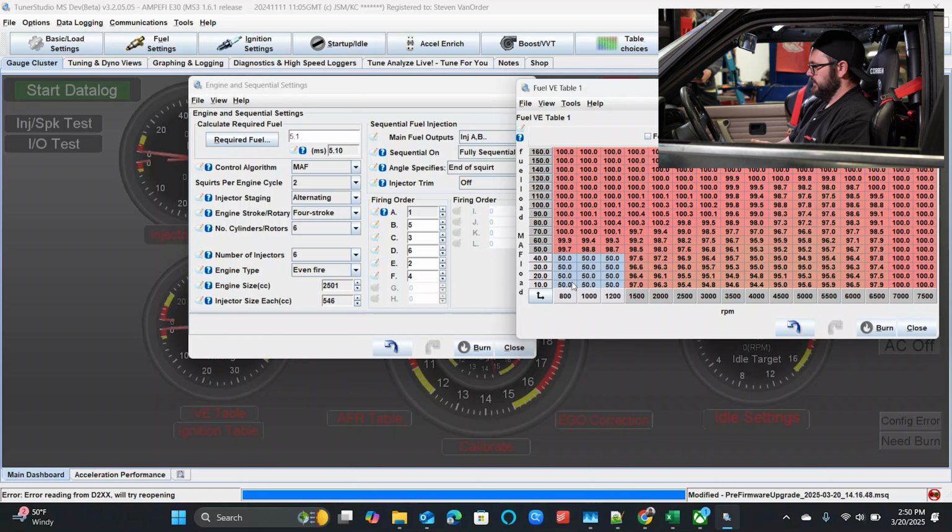which your VE at idle should probably be somewhere between 25 and 45 for most motors. It really depends on the engine, the camshaft. There's a lot of things that go into how efficient the motor is. That's a completely different topic. So if the VE table is a cylinder fill table, we can see how things directly correlate. At naturally aspirated, wide open throttle, you should be somewhere around 100 in your cylinder fill table.